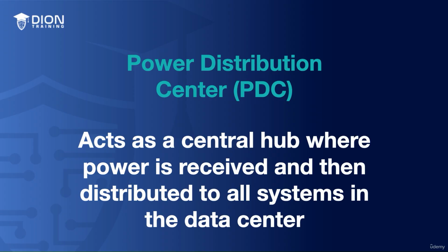Now, a power distribution center, also known as a PDC, acts as a centralized hub where power is received and then distributed to all of your systems throughout your data center. A power distribution center is not just a massive power strip, though, because it consists of a sophisticated system that uses integrated circuit protection, monitoring, and load balancing to ensure even distribution without overloading any of your circuits. A PDC can also be integrated with large uninterruptible power supplies and large permanently installed generators to ensure a seamless transition to a backup power system anytime you are experiencing a power event that creates a power loss event from your power grid.